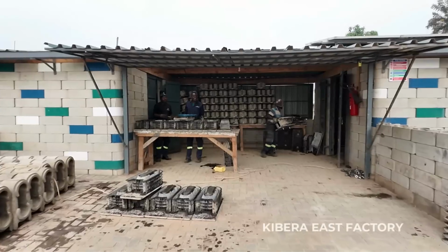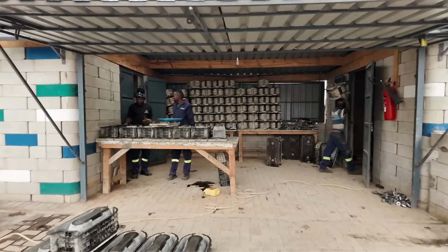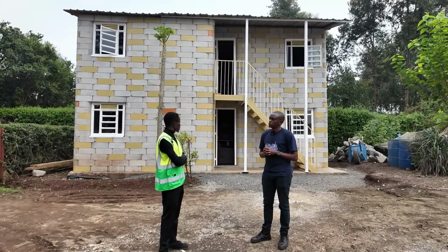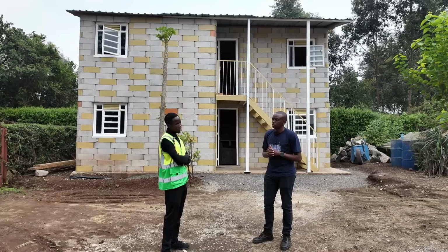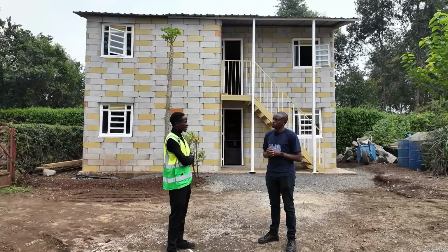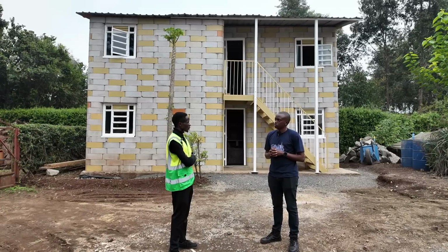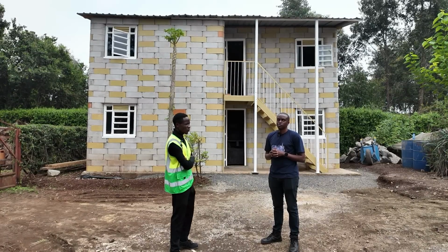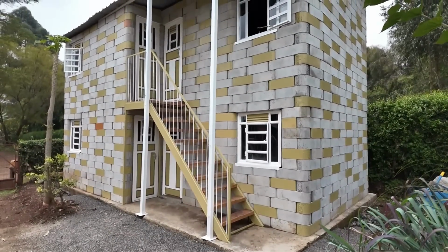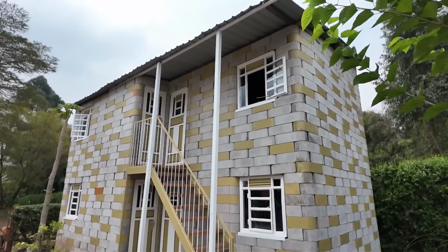You come to maybe our factories, and we're able to show you how we do different types of cuttings, like the special C cuttings and the round block cuttings using an angle grinder, and then you'll be able to use the blocks. Also, on top of that, we offer a service known as the block plans. We give the client every plan of the block from the first course to the last course. So with the block plans, using any fundi or mason, you as a client can adapt it and build as per the block plans and achieve it on your own.